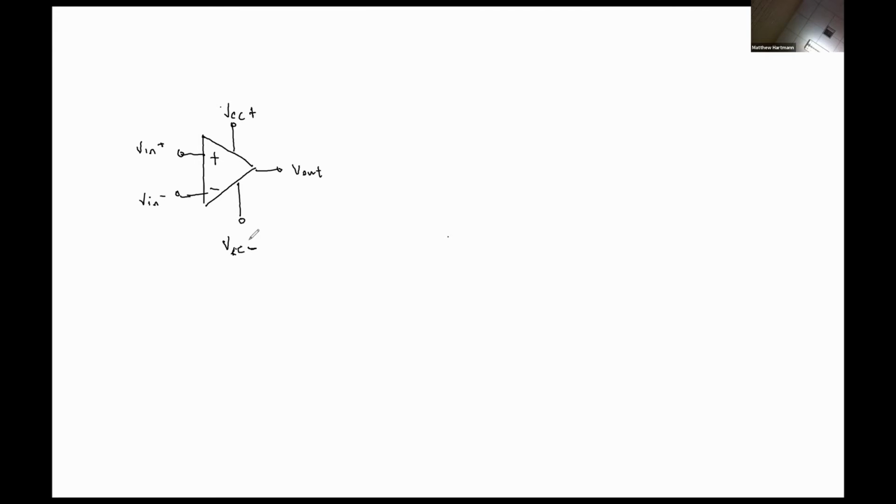It's called saturation distortion because an increase in the input signal does not cause a corresponding increase in the output signal. So we get effectively a hysteresis loop. I think you guys are probably familiar with what hysteresis loops are.